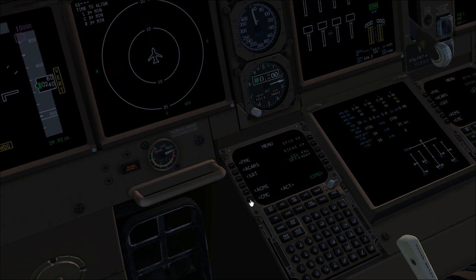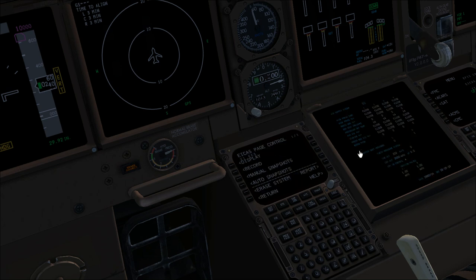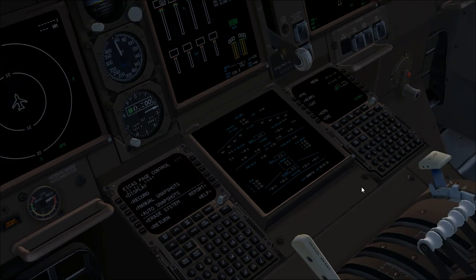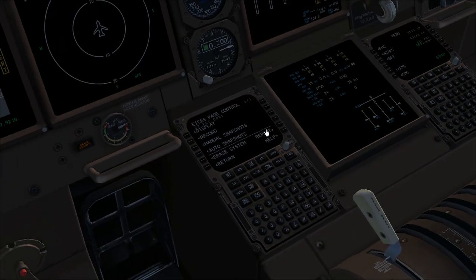Anyway, you have the CMC, that is the central maintenance computer. If you go there, you can do all the ground testing you want. We have plenty of them. If you enter a submenu, you have other ground tests, just like in the 737. You have the ECAS maintenance page, for example. If you want to check the HES, we can display it. You can see the HES maintenance page, or the flight control display maintenance page, or everything else we want to check. We are going back to the start page. Actually, you can really modify and test everything.